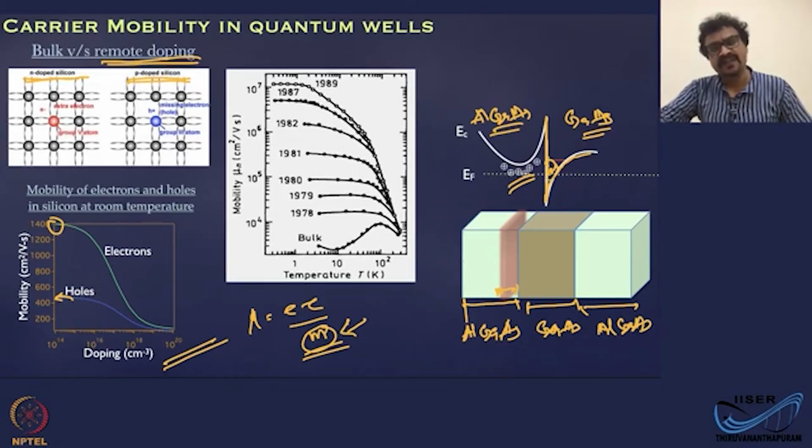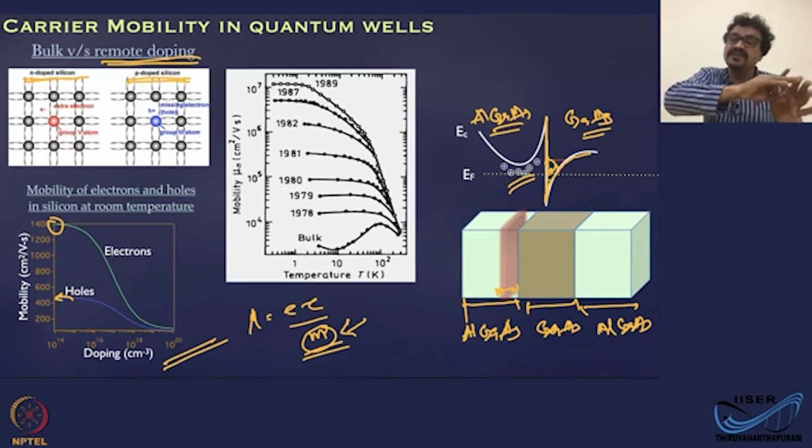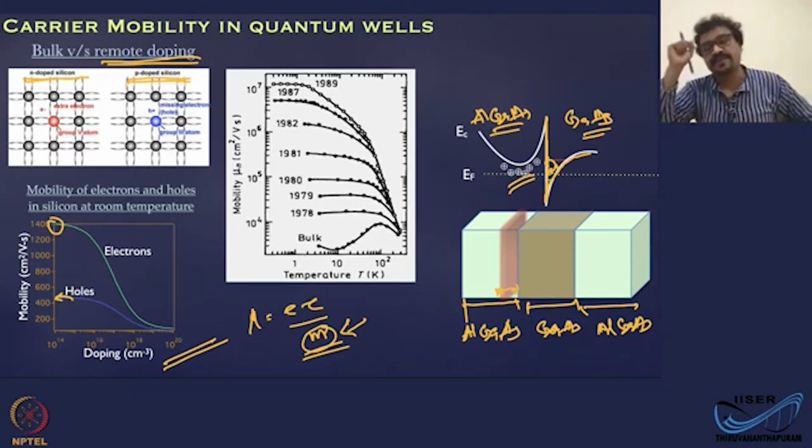That is the mobility that we discussed in one of the previous lectures, where the gallium arsenide, aluminum gallium arsenide heterostructure can have a few millions, tens of millions in mobility because of this remote doping. But you don't dope where the carriers move, you dope remotely. But the charge carriers, after ionization of these dopants, will end up somewhere else. That is the idea.